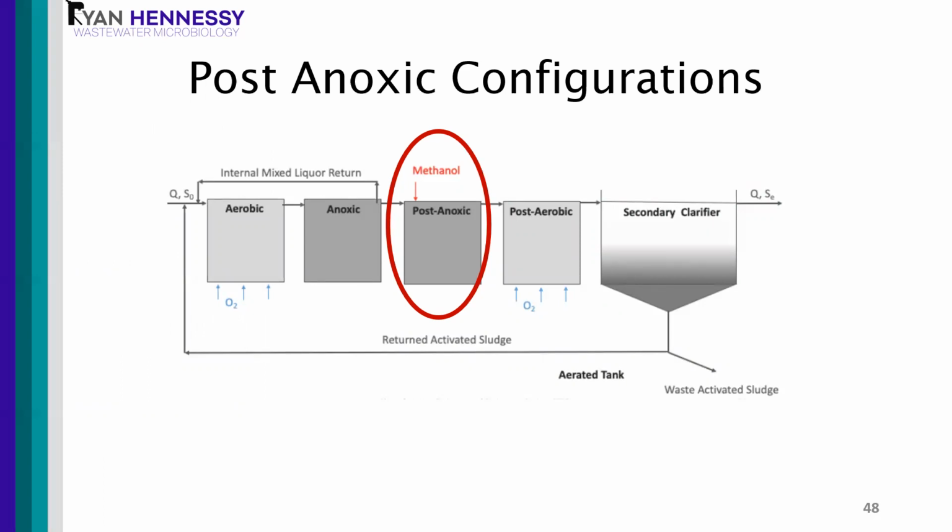So here, you're going aerobic, anoxic, and then basically there's still nitrate there, and they need to add methanol as a carbon source, which most plants are getting away from. There's some safety risks. There's some commercial carbon supplements. Sometimes industrial wastewater can be used, but here there's not enough BOD after it's already been through the aeration basin to really optimize denitrification.